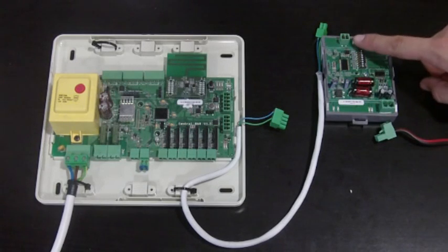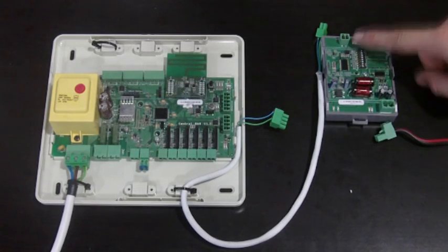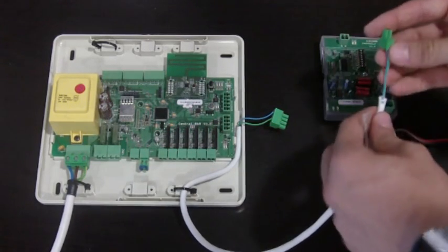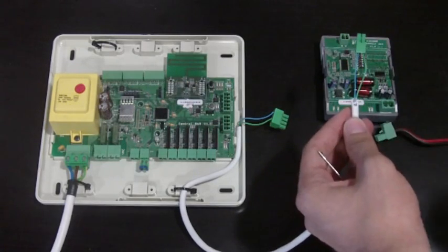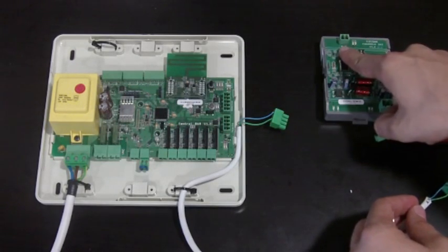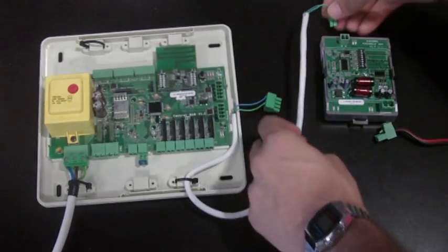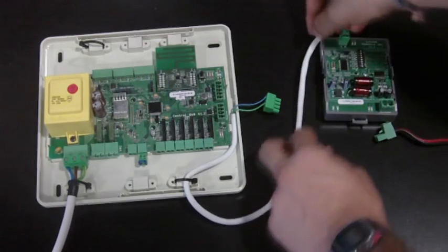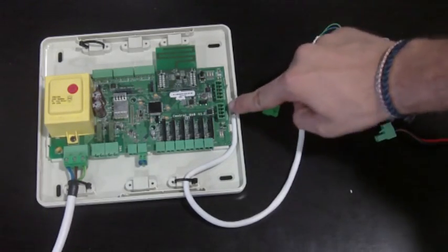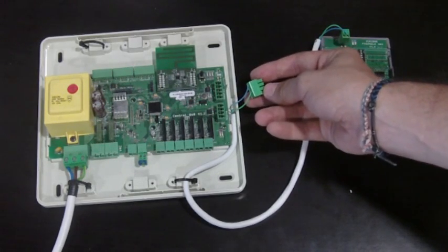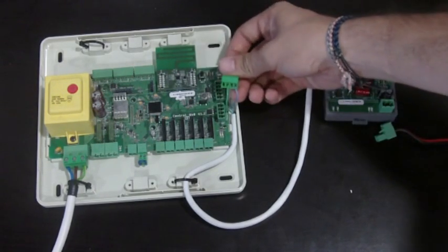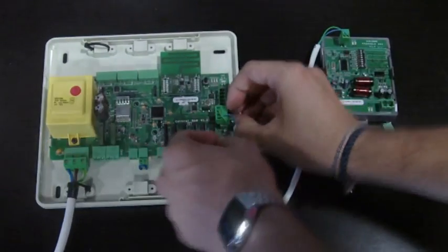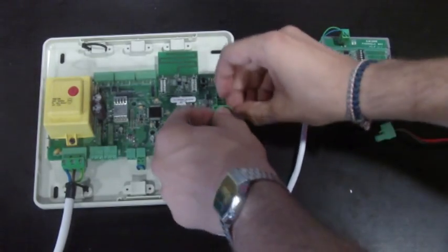The connector on the gateway for connecting the Airzone main controller is an aerial 2-pin connector. It is very important to respect the polarity of the connections. Bear in mind that this connection on the gateway side is accomplished with a 2-pin connector, while on the Airzone main controller side it is accomplished with a 4-pin connector. Hence, 2 pins will be unconnected. The connector on the Airzone main controller is placed in the same position for any product from January 2012 and on.